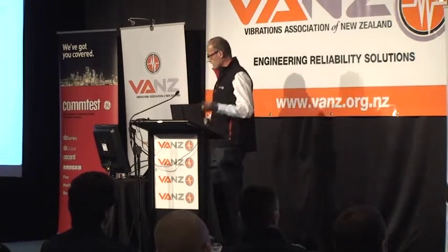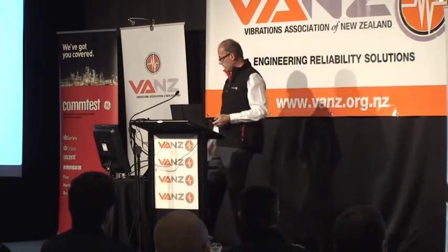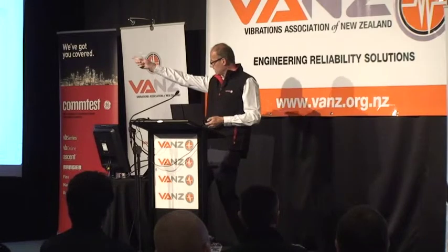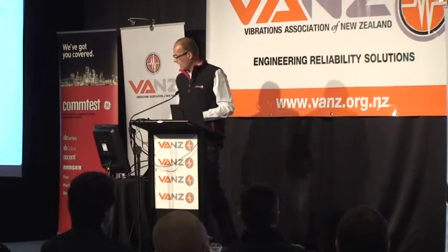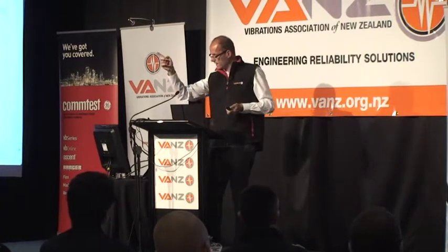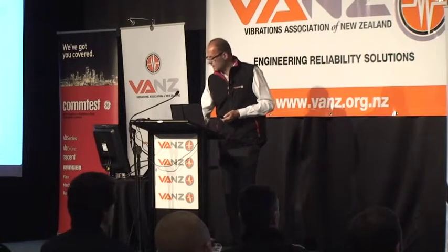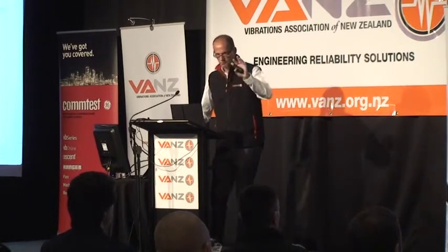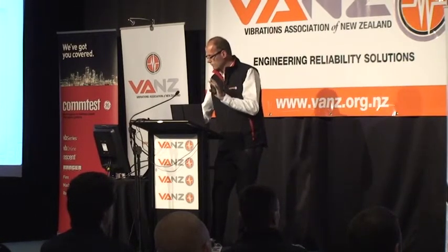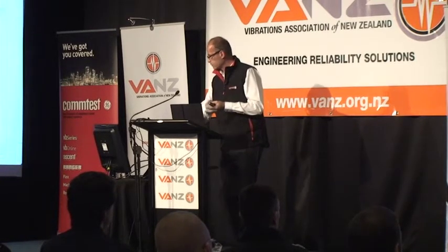So anyone who uses one of these tools and thinks, oh, I'm from the Wild West, slings it out and points it at a target a long way away, they're dreaming. They're just not measuring what they think, even if they've got a steady hand and can keep that laser beam right on the target. So we use thermal imaging instead. And with a tool like this, it's fantastic. We can get a much better picture of what's going on with the equipment and target problems.